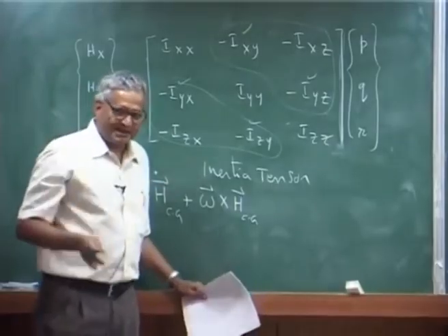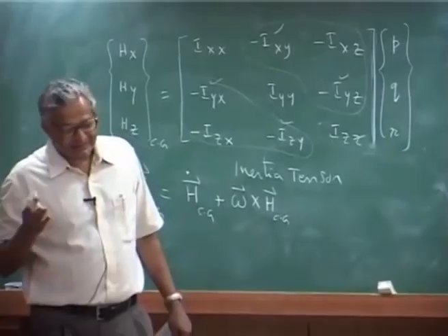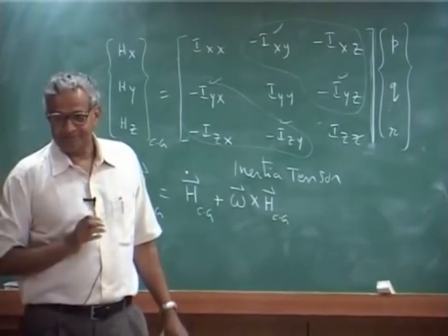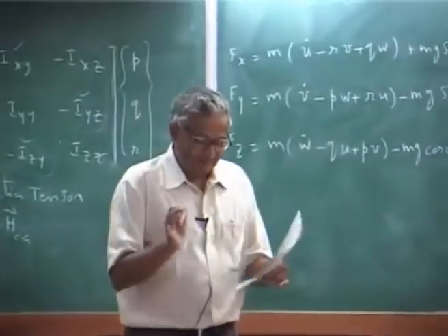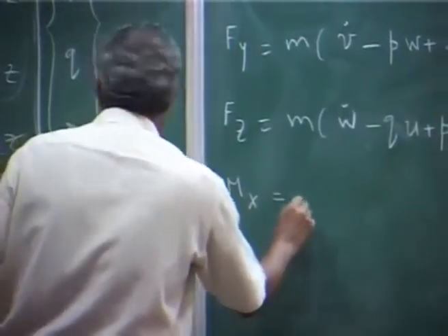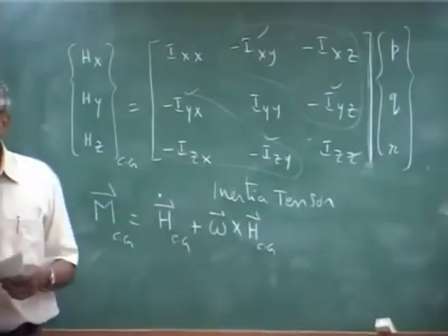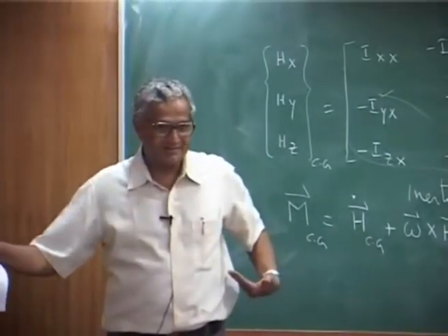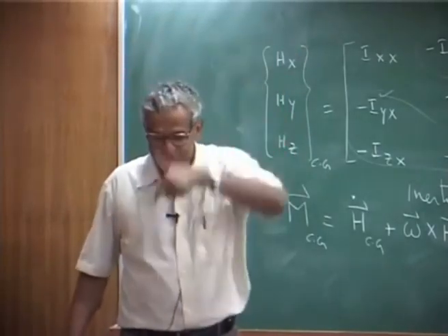That is because in the aircraft case, yes, there is a symmetry, but in the helicopter it is not exactly symmetric, because you have the tail rotor sticking out on one side. But you say that it is all right, let me make that assumption, because then I can write it in a smaller form. So, I will have my Mx, Mx is the moment of all the loads, that is the rotor loads, tail rotor, horizontal surface, every aerodynamic load, inertia, everything, transferred to the CG.